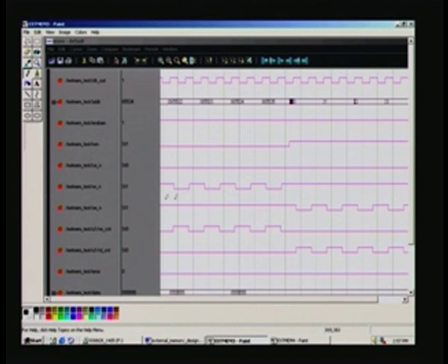Now you can see that the write pulse has stopped here because write is over with 65535, and soon after that this address changes to 0, and also that RWN control changes to 1 here, so that we can start reading, or I mean this being 1, it is a read only mode.